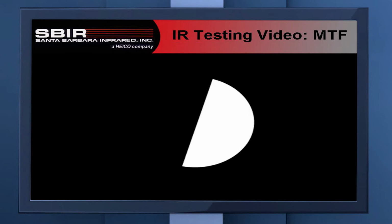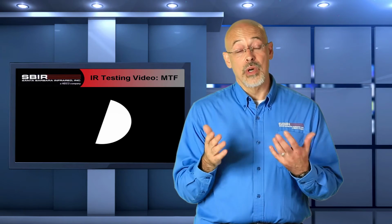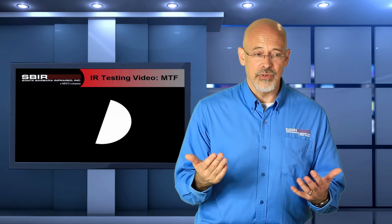But what if, in this next slide we show, the edge falls halfway along a sensor? Well, we're only going to get half the response from that set of elements. So when we look at the edge, there's this step function. It's nowhere near as precise as a single step. We have these multiple steps, and so we lose information.